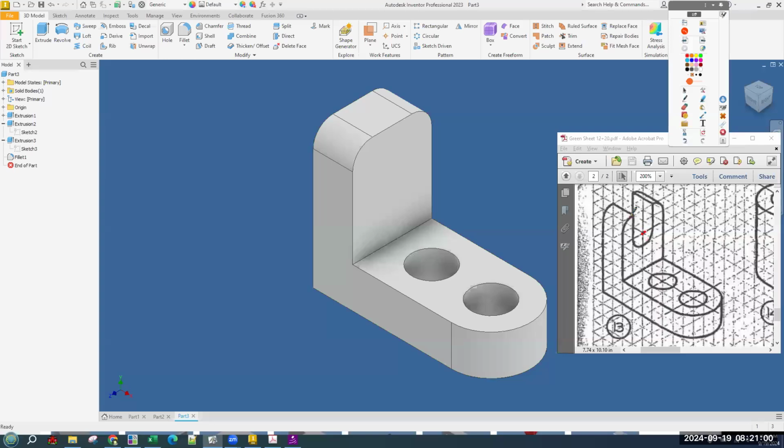It's a little tricky because we don't really have any snaps to use. So we'll make the center point, which is centered along this way, and it is a distance of 3 up. Actually, we're going to make the circle the right size, and then we'll dimension its location. We'll give it size and location.